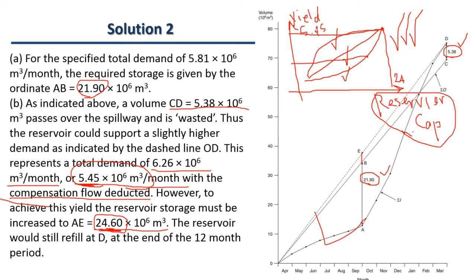Unfortunately, here in this example, it didn't explain other aspects. But in many cases, complications are not as simple as this. So you might have the situation of the reservoir with the highest volume, and if you don't have any flood overflow through the spillway, this is bad, because you might sometimes need to release the flow over the wet seasons, to make sure that the downstream can get the overflow of the flood. But it has to be safely passed.